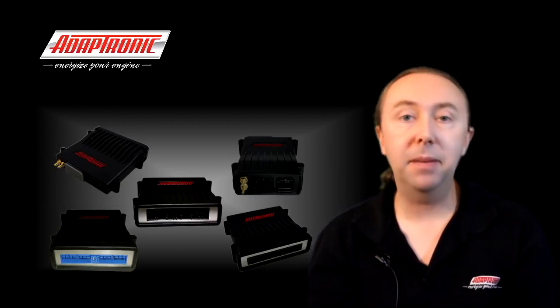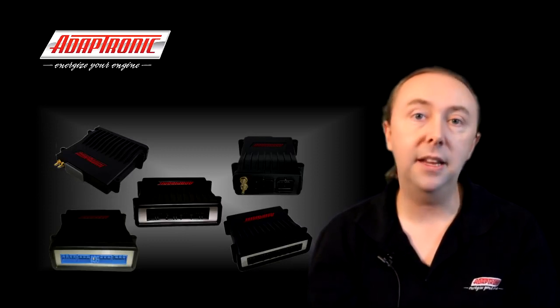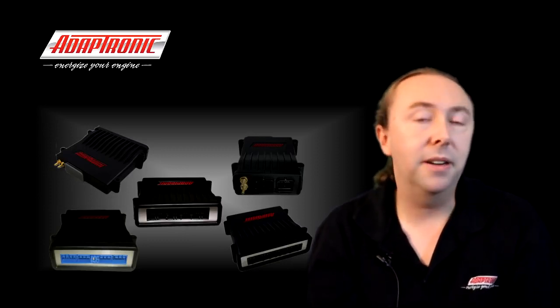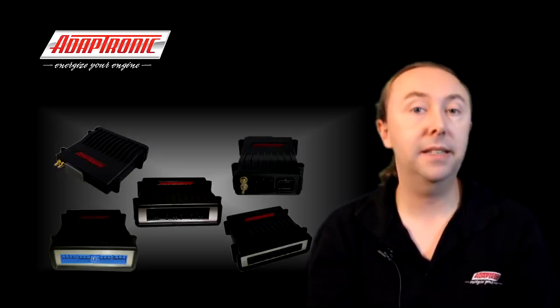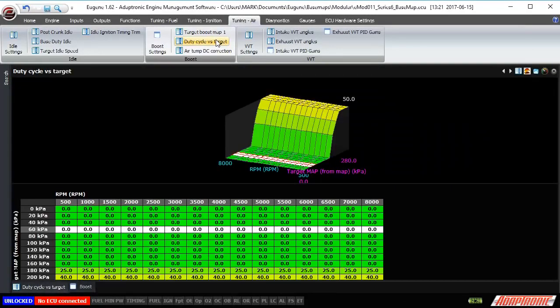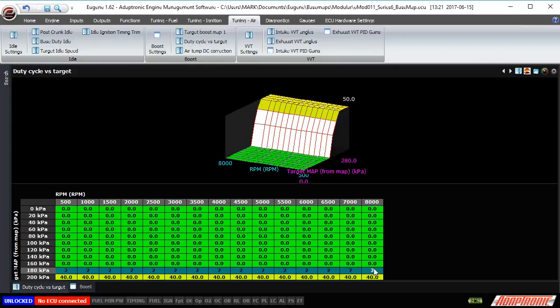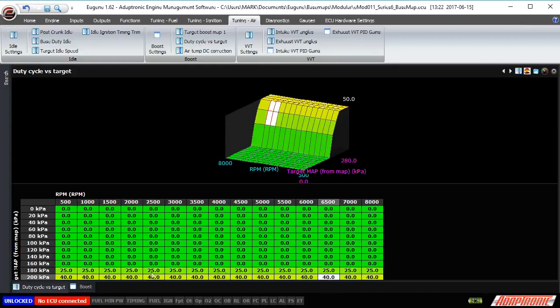So then that new target MAP becomes the target for the closed loop PID control, and the ECU also needs to work out the open loop duty cycle, the starting point if you like, from that target MAP. Now there are two ways to do this. The first way is with the duty cycle map. So in this case you have target MAP on one axis, RPM on the other axis, and the values in the cell are the duty cycle that you need to achieve that boost level at that RPM point. So that's probably the most straightforward way from the ECU's point of view, and from the tuner's point of view that gives you the most control. But on the other hand, it is quite fiddly to set up.